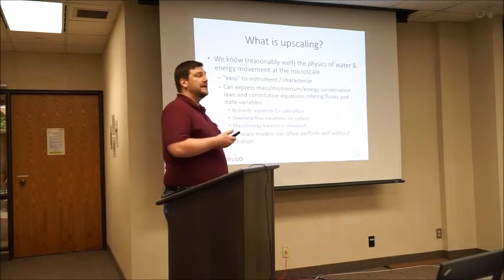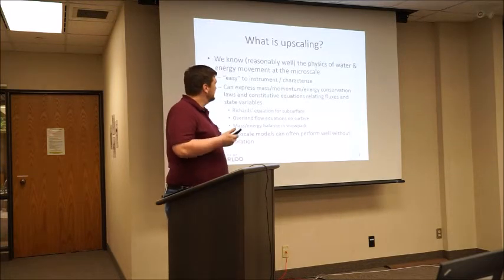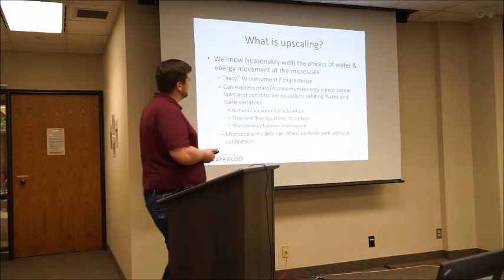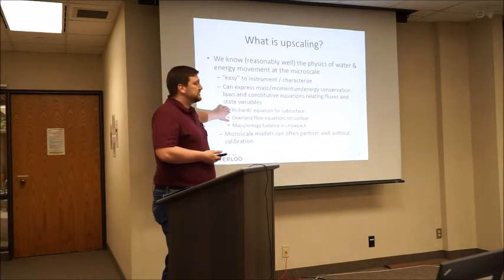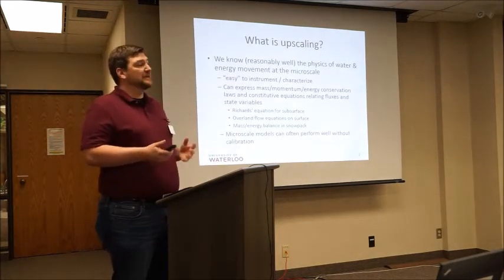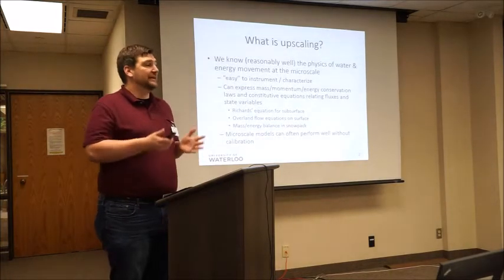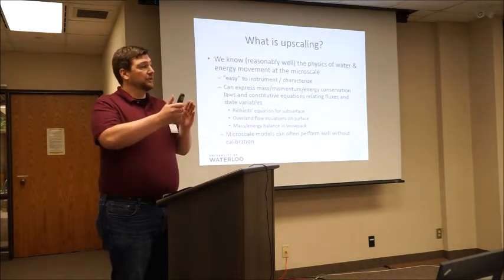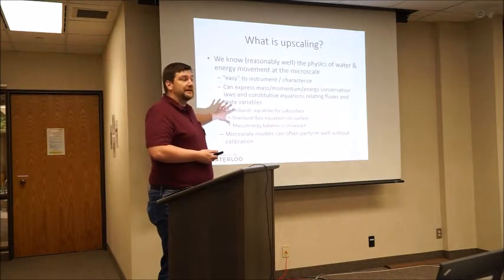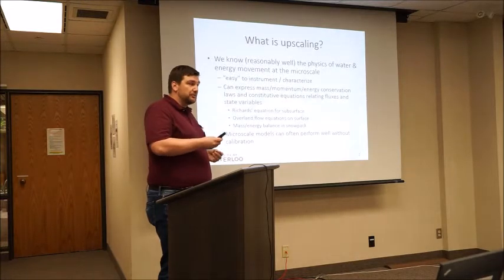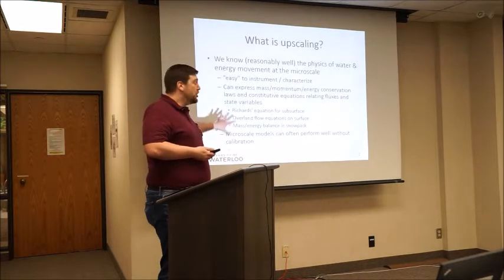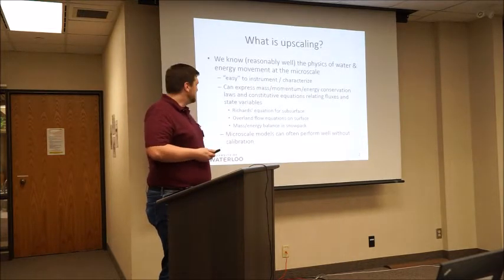So we can express mass balance, momentum balance, and energy conservation at the small scale. We end up with things like Richards' equation in the unsaturated subsurface, overland flow equations, and mass and energy balance in a snowpack. We can describe these in a great deal of detail at what I'm calling the microscale, the representative elementary volume scale. We're still not perfect, but because these are things that are measurable, we can focus in and zoom in at the small scale. We have a much better understanding, and we know the rules generally at these small scales.